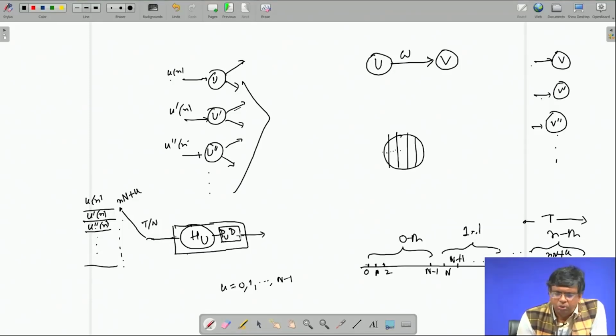Why do we need it? As I told you, the system is working at a faster clock, so we may often need to pipeline it so that it can process data at that rate. That is why some delays for forward path pipelining will come up. Those delays we are collecting separately for counting purposes only. Pu is an integer, and that very number of delays is used to pipeline it. These delays we are showing separately. So this is the situation.